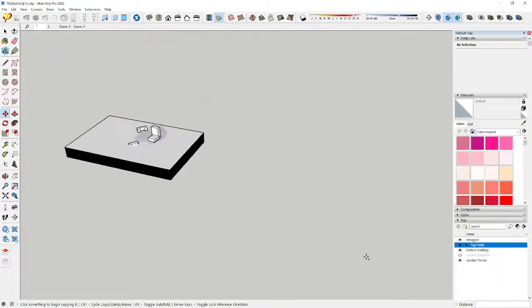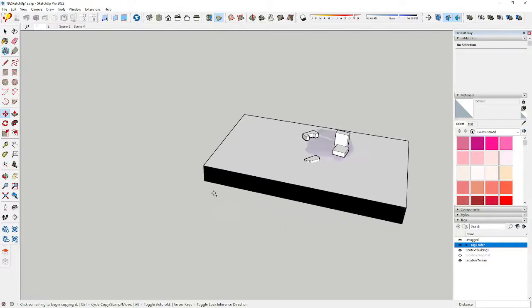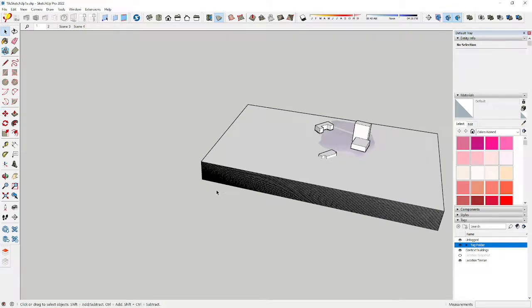And then once I saw that I had moved that 5 feet, then I typed in, without doing anything else, 30x, and that made 30 copies of that same move. Okay, now I'm going to hit the space bar so I can just select.